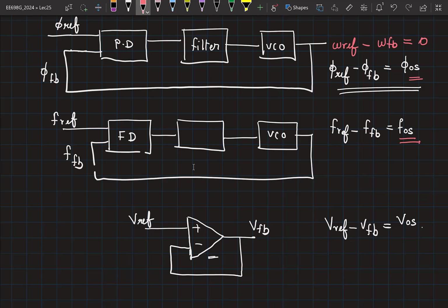Now, if you are thinking about a receiver architecture, you use a carrier frequency to demodulate the signal. And that carrier, the LO frequency, has to be the same as the carrier frequency in the incoming signal. Let's say your LO had a frequency offset. Then you are demodulating some noise instead of the information. You are entering into somebody else's channel. So that is a problem.